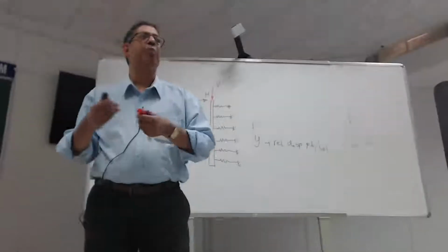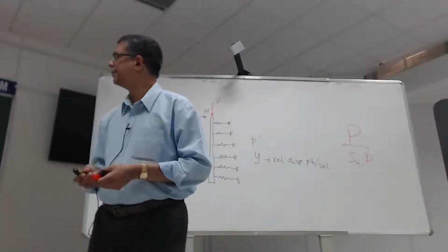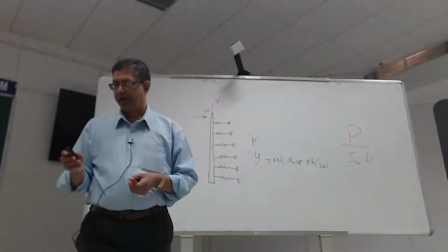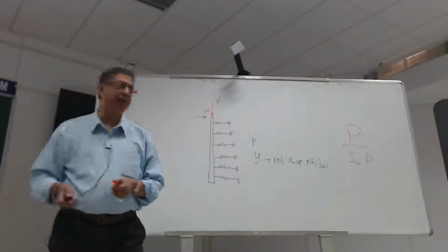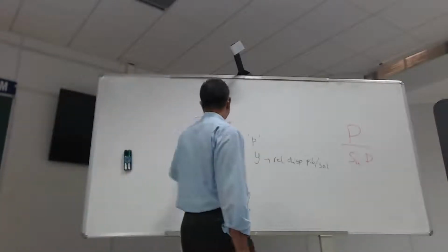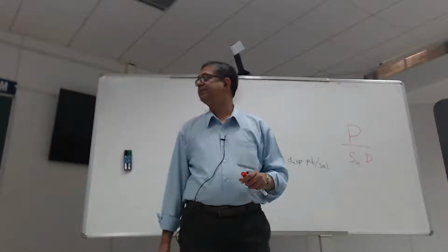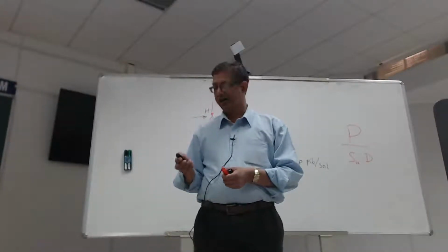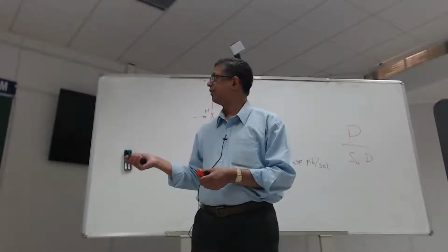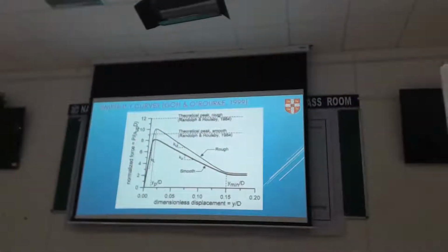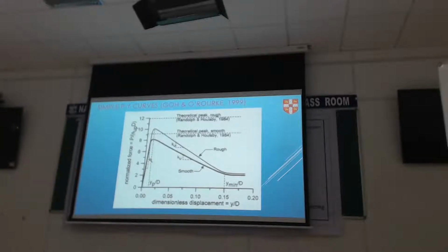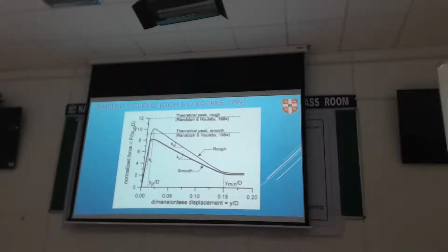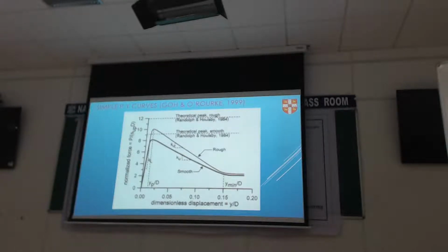So you can compare one with the other quite nicely. Because we are applying these now as limit states, you can also carry out upper bound, lower bound solutions, which Randolph and Houlsby have done a long time ago. So this is the worst case you can get. This is like a combination of upper and lower bounds, which means those are the true collapse loads.